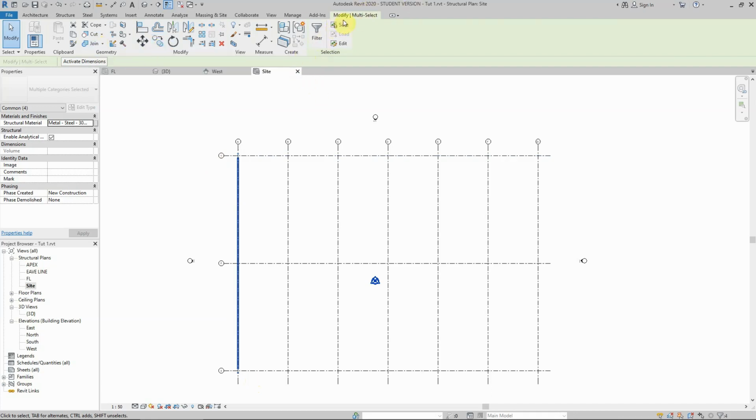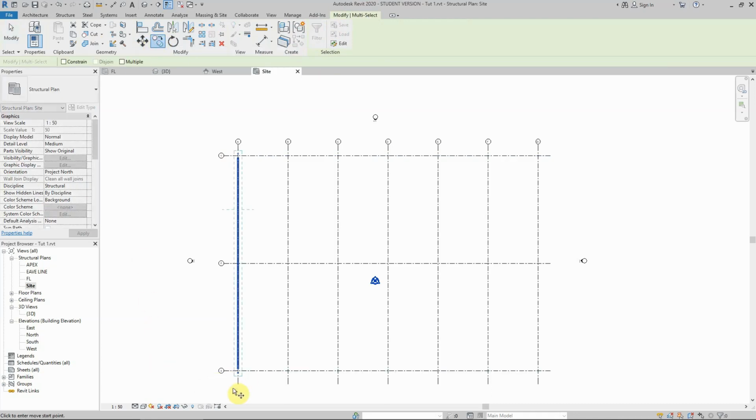So that will straight away take us to the modify tab. I can choose copy, and it's asking me what's your starting point, or what we call it base point in AutoCAD. If you are familiar with AutoCAD, that means where am I copying from. So I've got the members selected, but it's asking, okay, select that base point, and then from there we can start selecting distances.